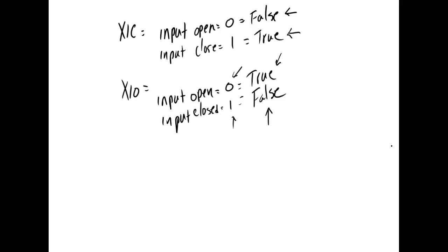It doesn't matter where you place the switch in the program. Yes, it matters a lot, because stop buttons, especially E-stop buttons, according to OSHA, have to be normally closed. Because if you've got a normally open switch and one of your contacts wears out, which happens all the time, it won't work. And you're sitting there beating on that normally open switch with a bad contact, and things don't stop. I understand the physical switch needs to be whatever. I'm saying if you can change a normally closed contact to examine open.